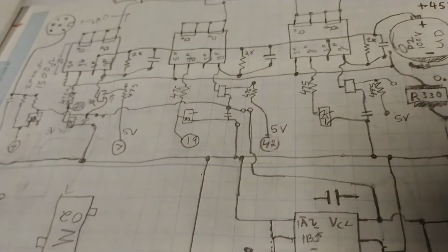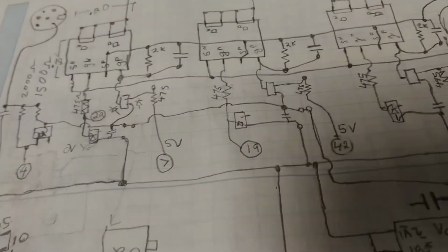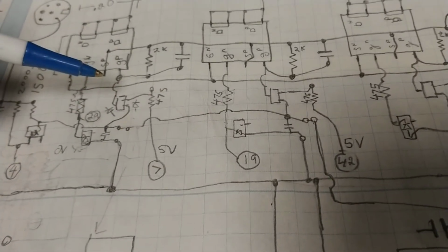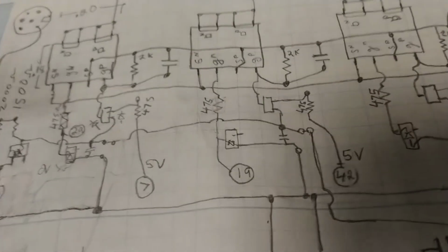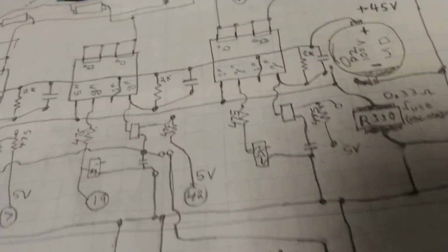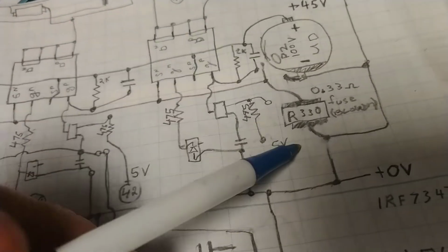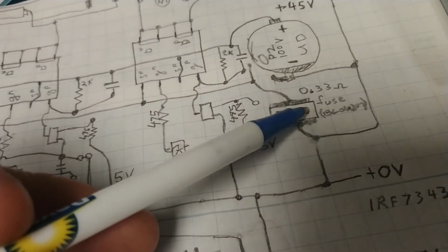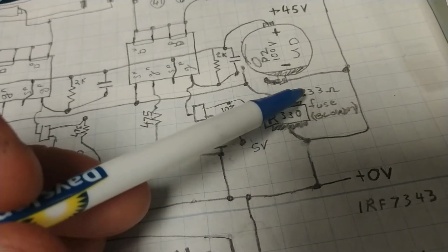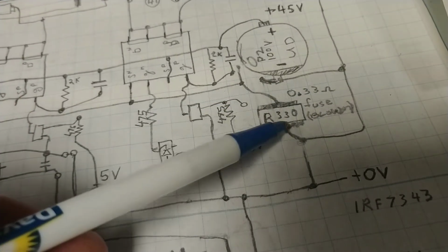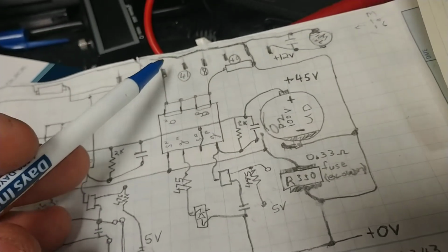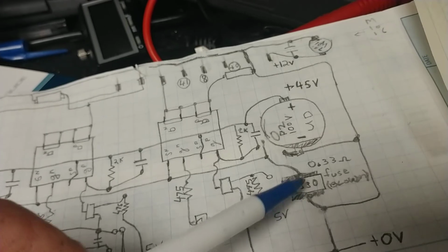Back to the hot plate in question. See if we can identify some safe. So, the hot plate in question. What was burned out on this? Looking at the microscope and also using the ohm meter, R330 was blown. It's acting like a fuse. R330 means 0.33 ohms. All the amps that are going out to the motor coils have to go through that.